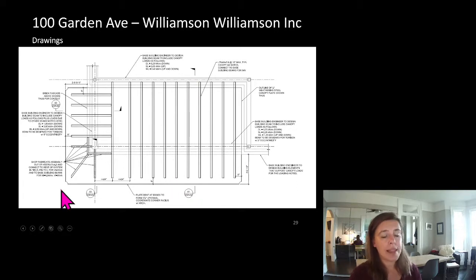We also had the issue that we had to worry about drainage. So this point here needed to be the lowest point on the roof. So we couldn't put framing around in any way that would retain water back somewhere. So we needed water to be able to flow out and hit an edge and get to a drainage point.